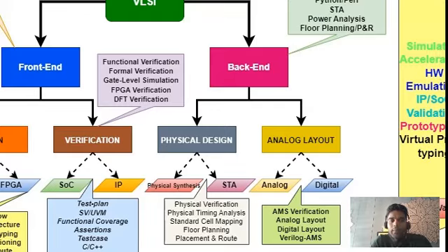And if you can modify the standard cells, the characteristics, you can do it on your own, or you have to get back to the design team and give them feedback that I'm observing this particular design is not meeting my timing requirement. Can you go back and look into your design and fix it? So that kind of loop-back work has to happen in order to fix those timing issues.